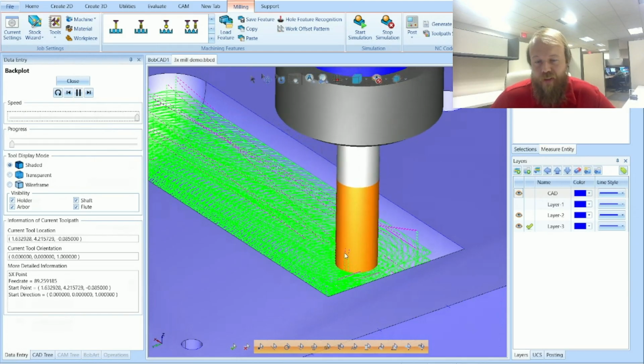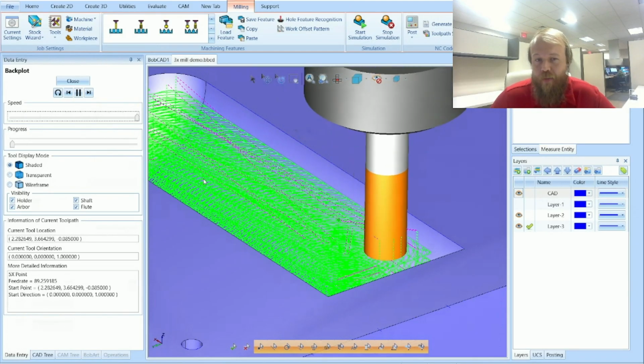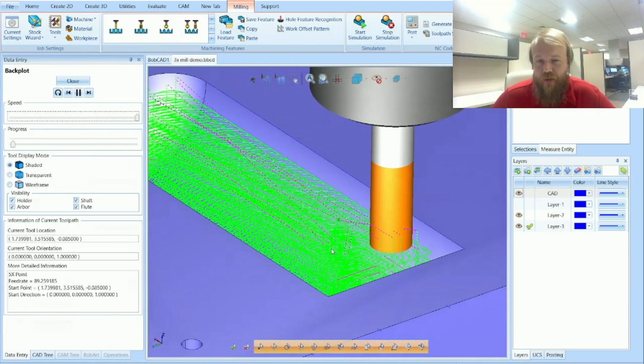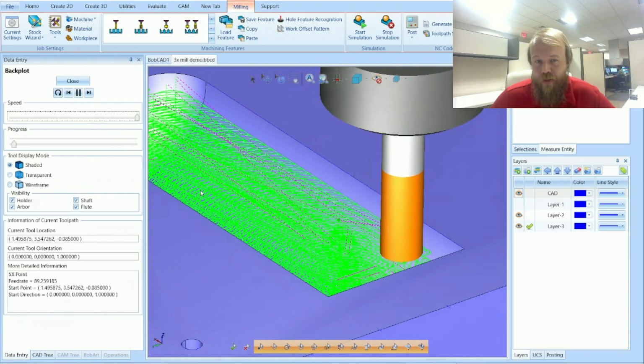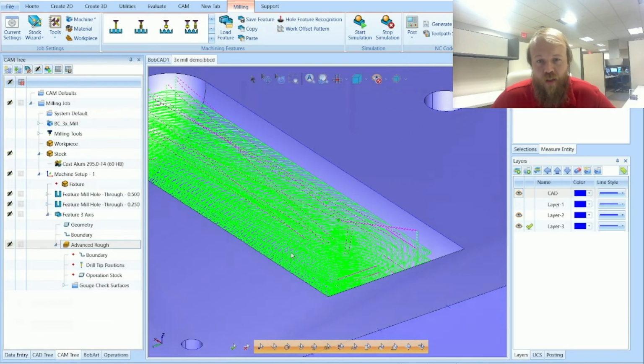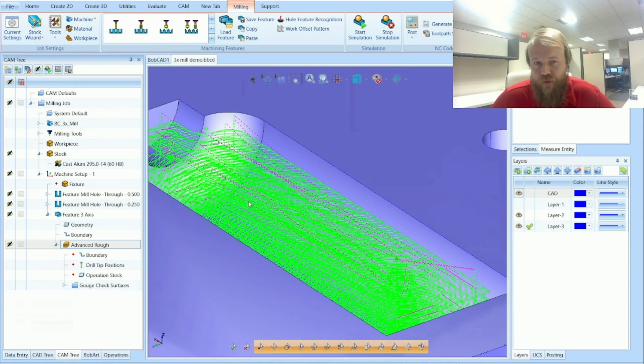And I can have it start at a different location by plotting a point in the CAD geometry and selecting that point as my position I want to plunge down in. So if I've already drilled a hole closer up here, towards the bottleneck of the bottle, I can plot a point there and have the milling tool plunge into that area at each depth so that it starts where I've already drilled that hole.